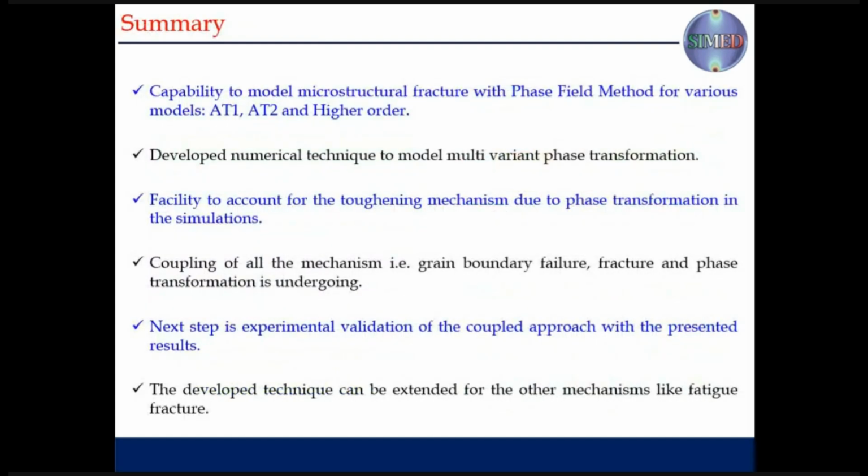So the summary of this research is that we have the capability to model the different types of softening using the phase field model, like the AT2, AT1, and the higher order phase field. We have developed the numerical technique to model multivariant phase transformation, and built the facility to account for the toughening mechanism, and coupling of all these mechanisms is undergoing. And with this coupling, the next step is to experimentally validate these results. And this developed technique can be extended to fatigue fracture.